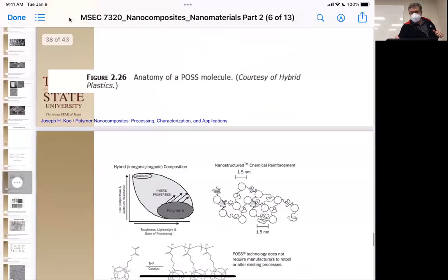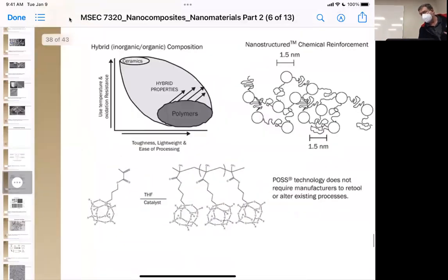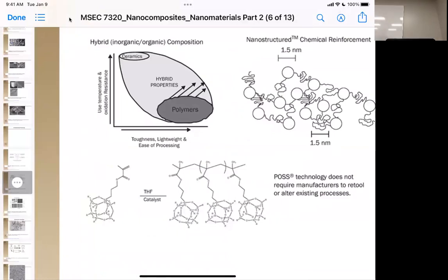Okay, so if we look at what that kind of looks like, why is it nanocomposite? We see that these right here are a volumizing bulking agent. So if you want a nanocomposite with selective gas permeability, that means you want a certain amount of free volume in your system, and you want to have it consistently all the way through your polymer so that your gas of choice diffuses at a specific rate and slows or speeds up everything else. And you end up getting just one gas.